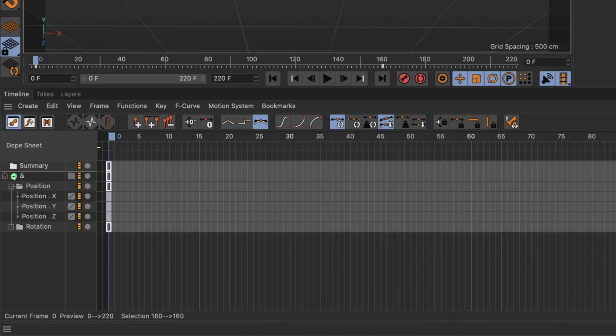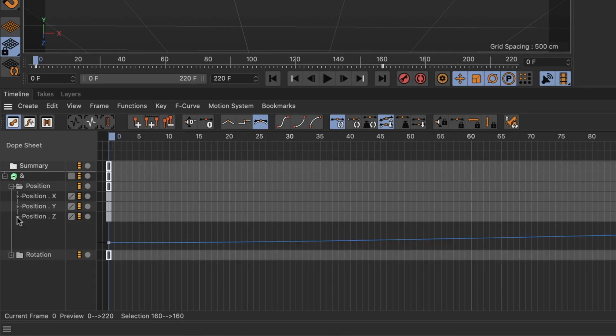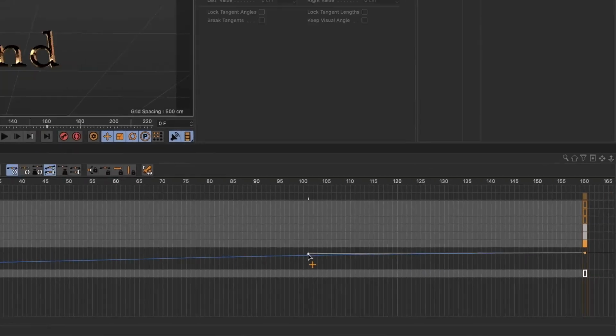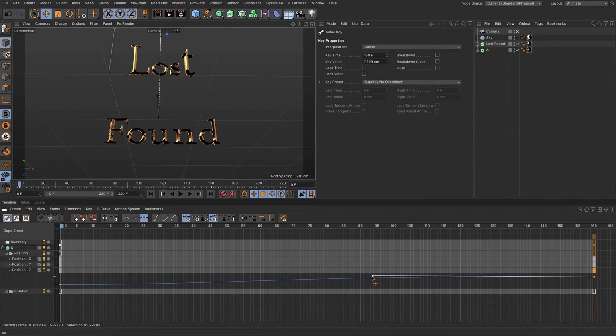Options we have for keyframes involve looking at it with a graph. And in fact, if I twirl down this little arrow next to position, we can see here that we do have some easing on our position Z keyframe. I'm going to drag on the handle here just to add some more easing. And I'll see an update right there inside my viewport. I'm actually changing its